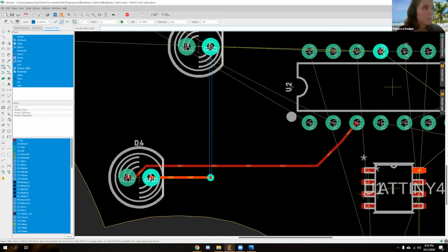Like, it doesn't necessarily snap to where I want it. It's not snapping to overlap with where the wire is. Yeah, I think I have an idea of what you're saying. Are you trying to route something to the little microcontroller? No, so when I place that, start with a V, a little circle thing. Okay, the via. So I click the little circle thing to place it, but it doesn't actually line up with the red wire that I have.